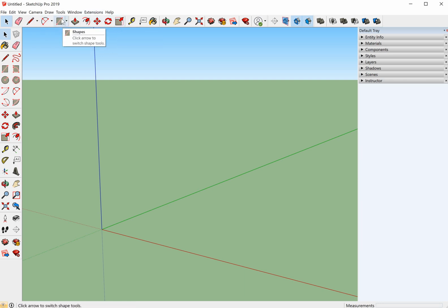And to start off, we can draw a flat 2D shape, and this button gives you options of different shapes you can draw. You can also draw different shapes using the same shapes that appear in the large tool set, or you can draw shapes using a line or arcs. So I'm just going to start off by drawing a rectangle. And I'm going to use the push and pull tool to give it dimension. So I just selected an edge and pulled it up.